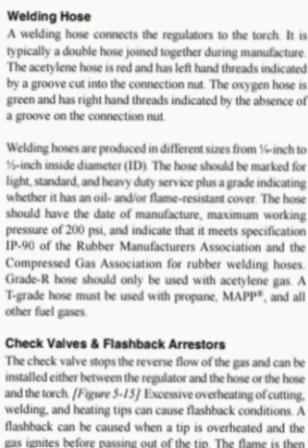Check valves and flashback arresters. The check valve stops the reverse flow of the gas and can be installed either between the regulator and the hose or the hose and the torch.